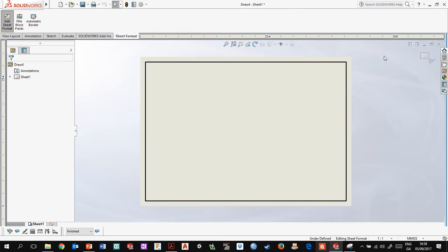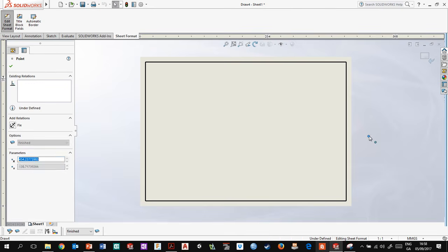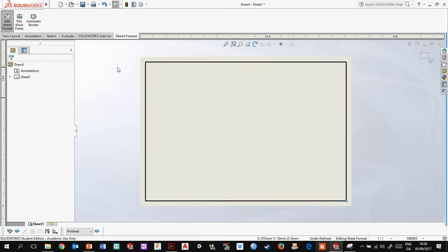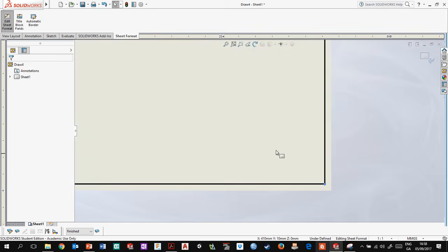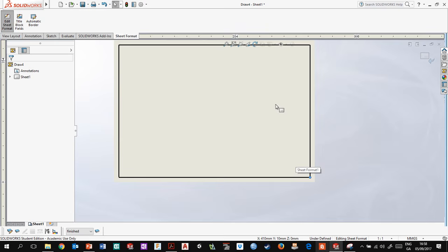So this is kind of like a sketch, and there's one thing about SolidWorks that you'll notice that's different to AutoCAD is the sketches can be dynamic. So for example, this rectangle here it's possible to move it around, and there are points on it that you can move around. So what we want to do is we just want to get the bottom corner of this rectangle. We want to make it fixed so that it can't move, and that's just defining our geometry. We'll go more into that as we go through sketching and part modeling during the semester.